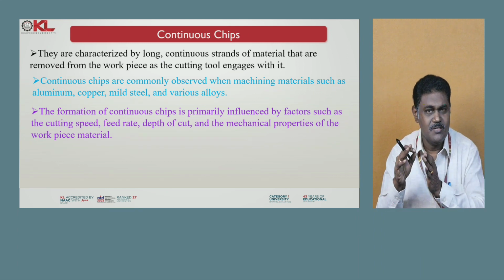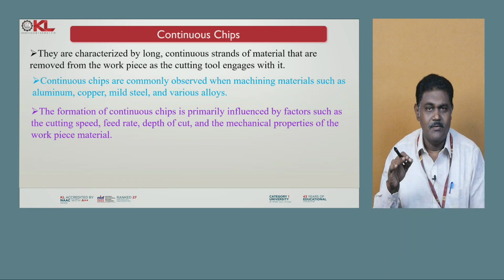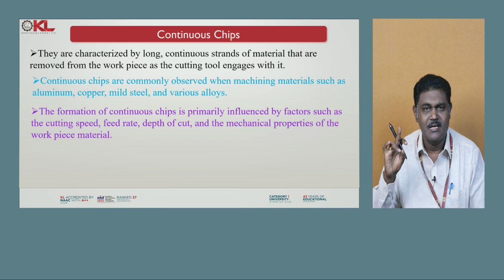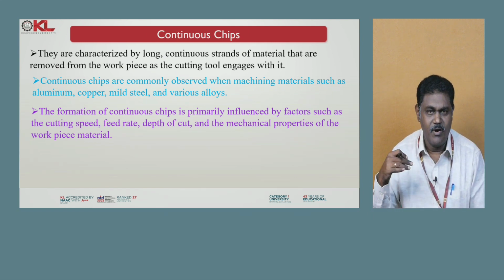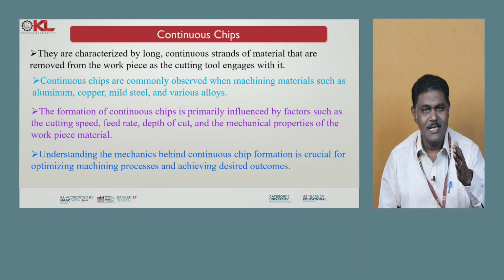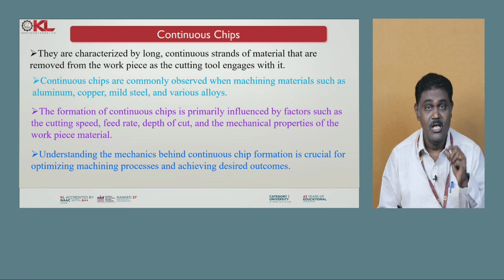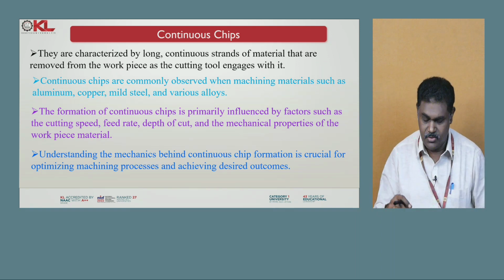So the continuous chips mainly depend upon these machining conditions, mainly the cutting speed, feed rate and depth of cut. They influence the formation of the continuous chips. Understanding the mechanics behind continuous chip formation is crucial for optimizing machining processes and achieving desired outcomes.